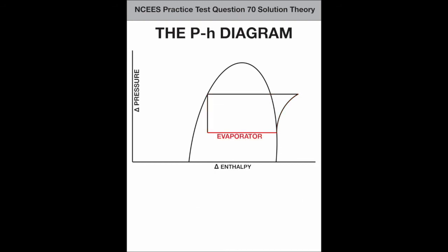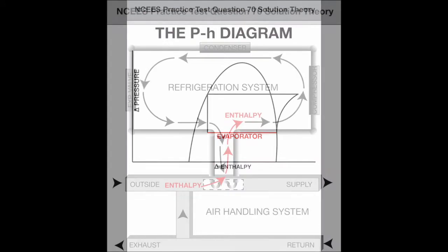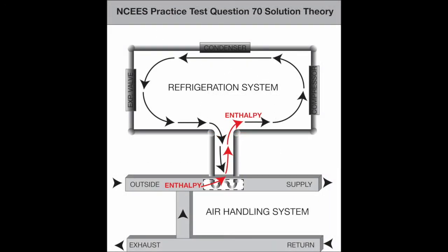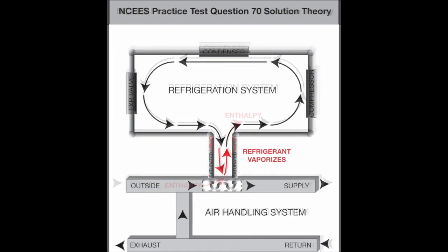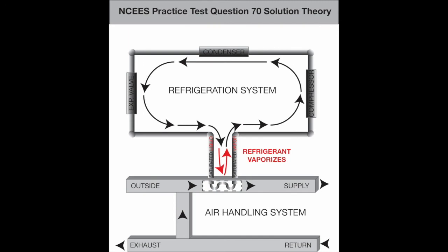This demonstrates the operation of the evaporator. When exposing the saturated refrigerant to the air it must cool, the refrigerant pulls that air's heat energy into the refrigeration cycle. This causes the refrigerant to increase in enthalpy, and in doing so, to vaporize, but not to increase in temperature.